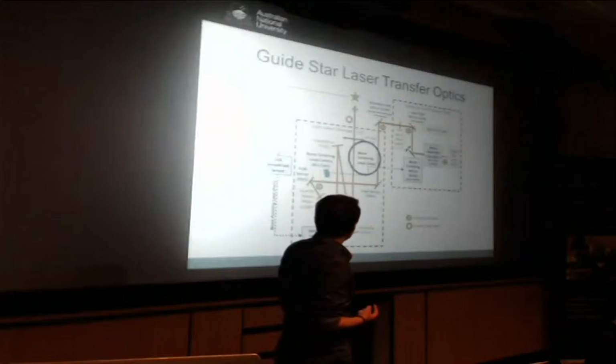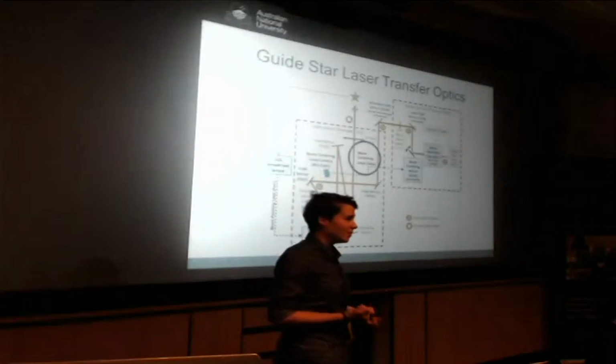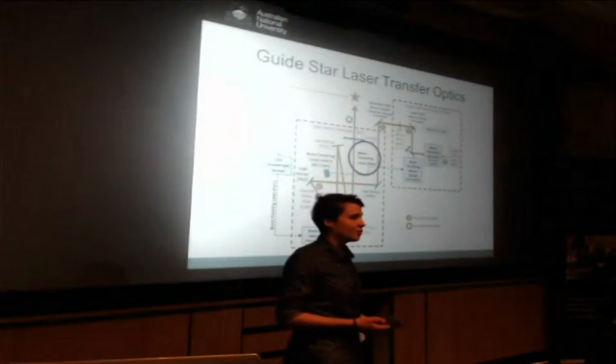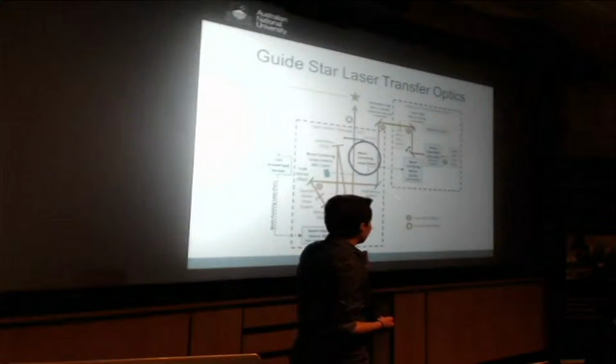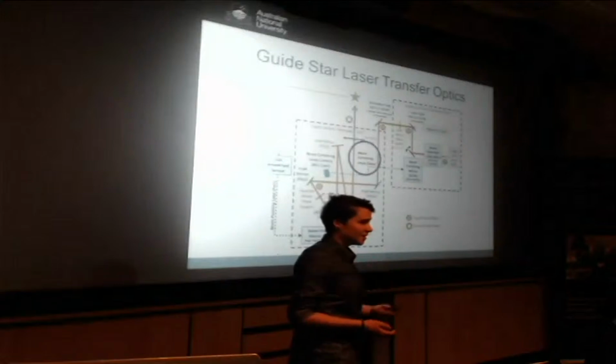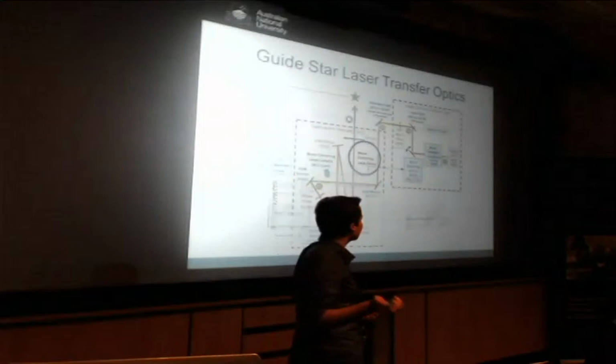We have a beam centering loop camera, which images scattered light from the surface of the beam pointing mirror in order to provide feedback information on its alignment. The actuator in the system is the beam centering mirror, or BCM over here, which is continually controlled in order to correct the alignment of the laser beam.